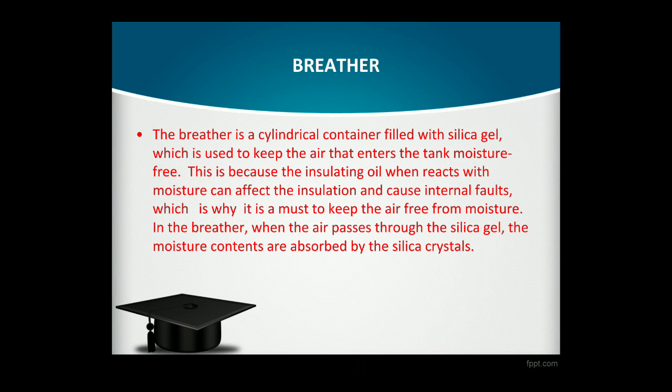The actual color of the silica gel is blue. When it is saturated by water, the color of the silica gel is converted into pink. This is because the insulating oil, when it reacts with moisture, can affect the insulation and cause an internal fault. So we can't allow moisture, which is why it is a must to keep the air free from moisture in the breather. When the air passes through the silica gel, the moisture content is absorbed by the silica crystals. And when the color of the silica gel is pink, we have to replace it with dry silica gel, which has the blue color.